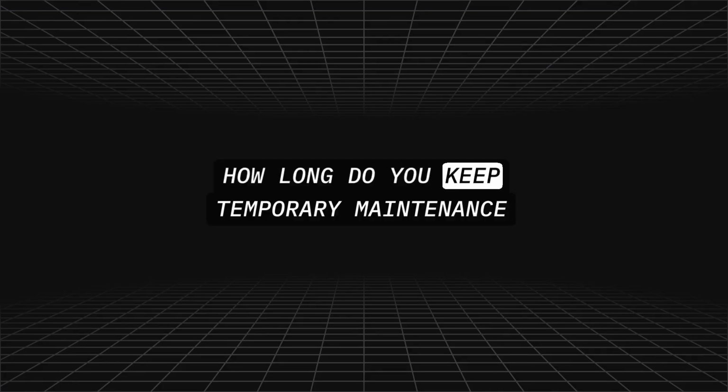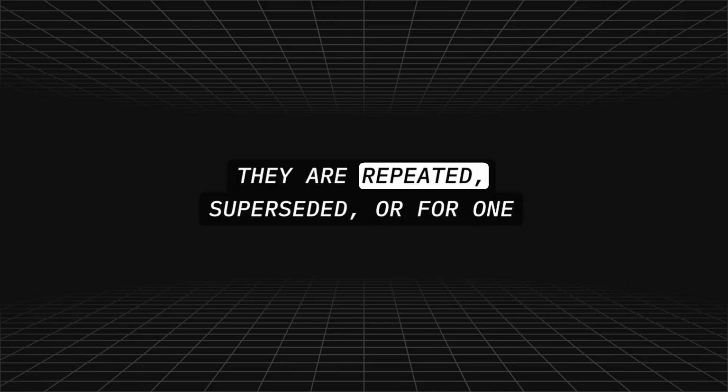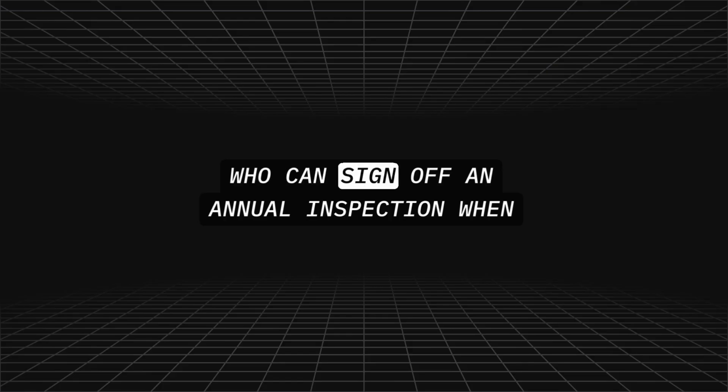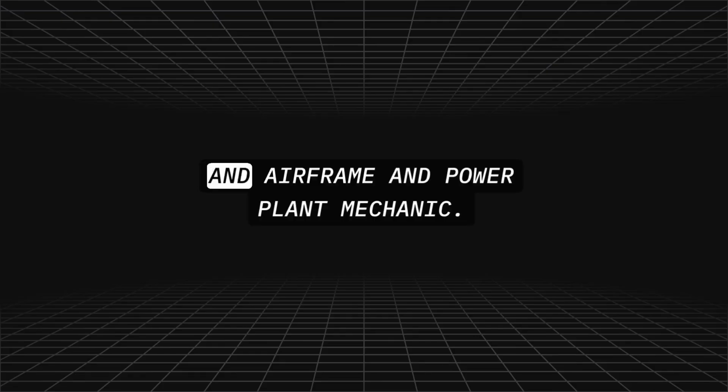How long do you keep temporary maintenance records? You must keep temporary maintenance records till they are repeated, superseded, or for 1 year. Who can sign off an annual inspection when the airplane is deployed? An airframe and power plant mechanic.